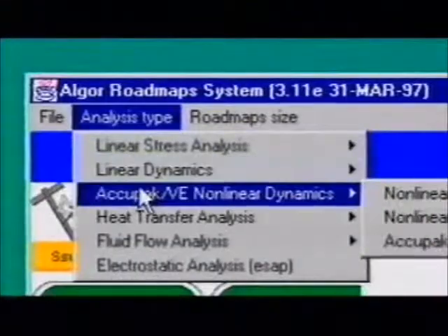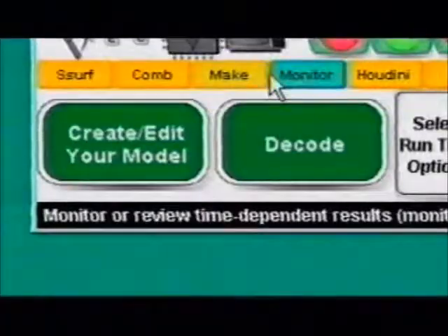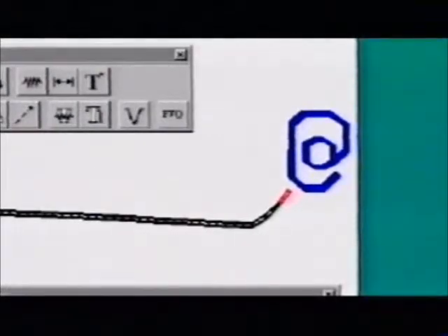We began the analysis by building a 2D finite element model using Algor SuperDraw. The critical part was modeling the spherical shape of the bottom of the can. Note that the edges are fixed to resemble the way the bottom is attached to the real can.